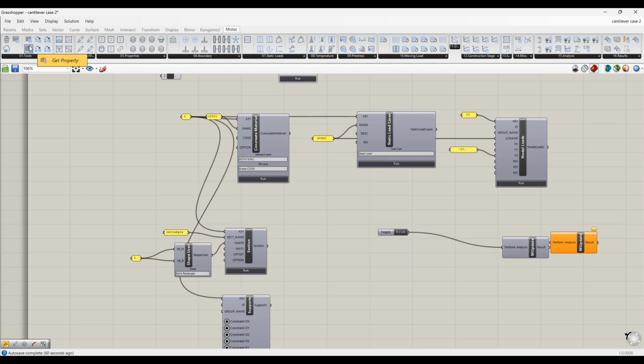Here there are different tools to get the property or get the MIDAS nodes and so on. Let's say instead of geometry modeling in this Grasshopper, I can first create the geometry in MIDAS Civil NX and then call it using the MIDAS get option. There are node and element options, and these are for different groupings.